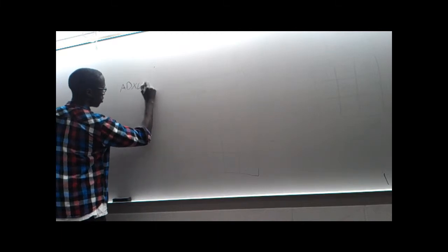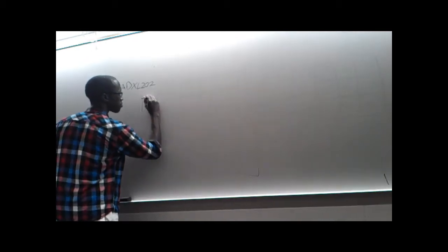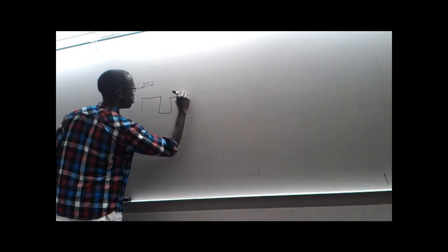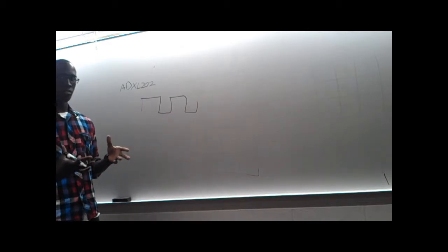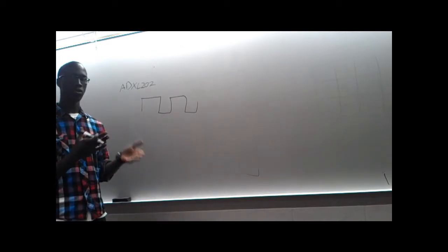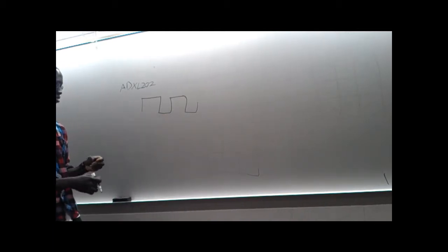Hi, my name is Kojo, and today I will be talking about the ADXL202 duty cycle modulated accelerometer by Analog Devices. And basically what that means is that you have this G-force sensor that, depending on how you tilt it, modulates the duty cycle of an output signal.